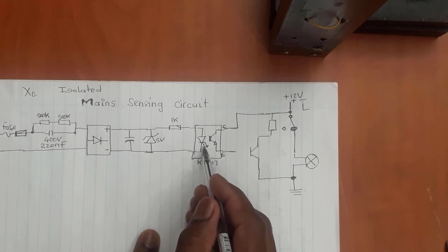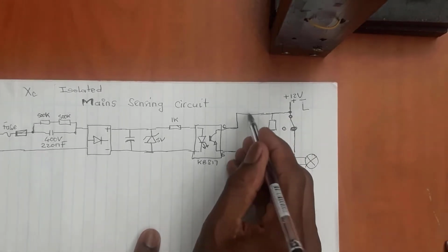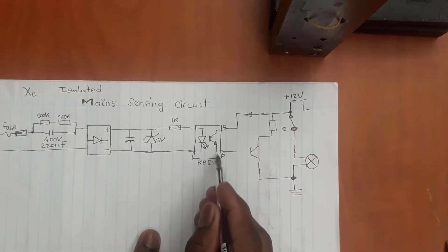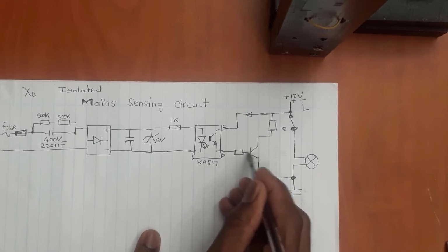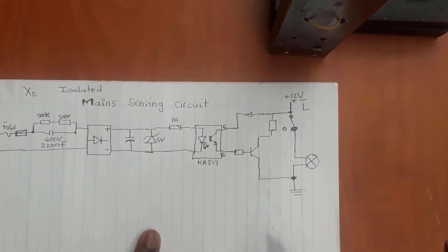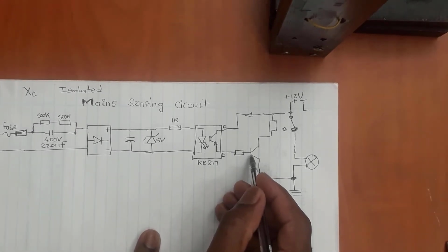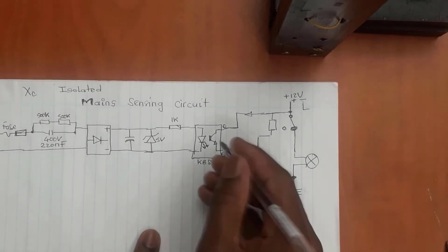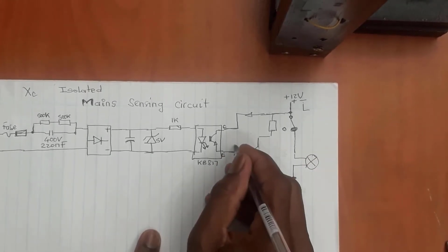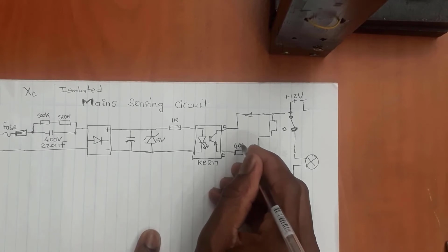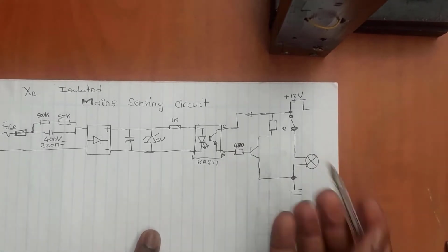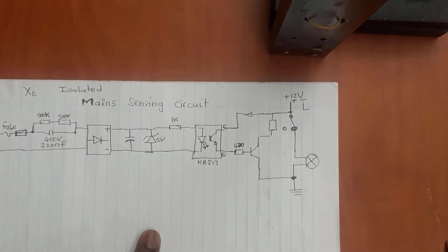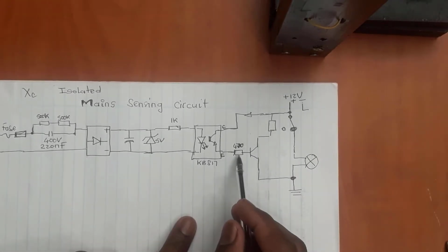The LED is on, the transistor is biased, so we've got conductivity, so current will flow like this, and that in turn will induce some current here, and then we put a resistor here to the base of this transistor to bias it. We can put, I don't know, a 470 ohm resistor, it doesn't matter. We can calculate how much current we set for this transistor. That will basically mean the circuit is completed.